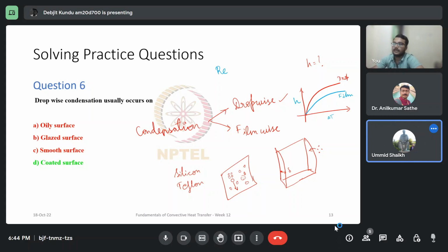See, while calculating Reynolds number for any case, there has to be a characteristic length. Now, in this case, the length would actually go on. So if I take this x direction, we don't stop at any L. This could go on forever, right? So this dimension is not bounded. That is why the width multiplied with some unit length, 1. So width into this unit length 1, this is taken to be the perimeter.